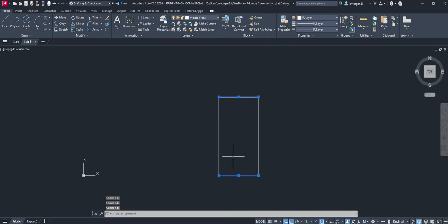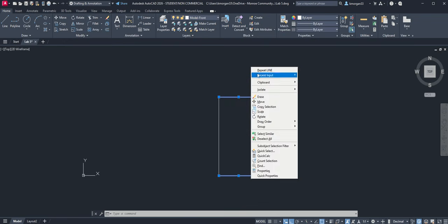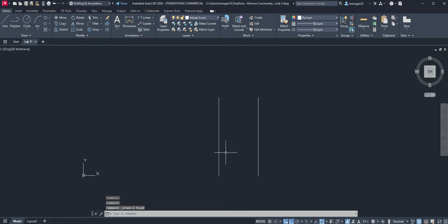Okay, so anyways, don't click control. It was a different version, the 2026 version, so you click on this 2 line, and then of course you erase that. Now you have a perfect horizontal and vertical alignment. Once you finish it, if you want to turn off the auto mode, you click F8, and it will go back to the normal mode.